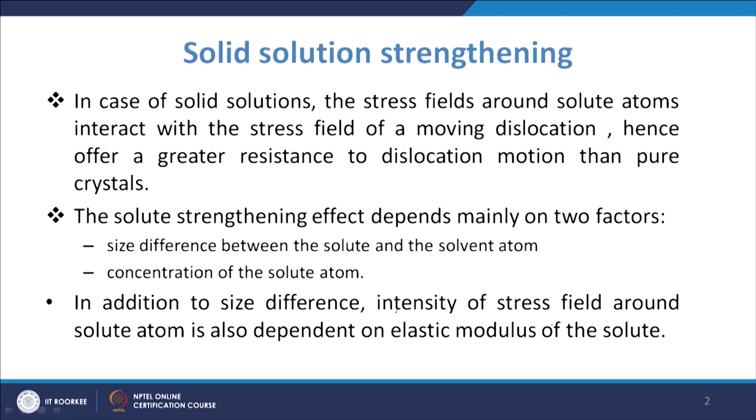As we discussed, in solid solutions the stress field around the solute atoms interacts with the stress field of a moving dislocation. These two stress fields interact with each other, and in that process a greater resistance is offered to dislocation movement in solid solutions than in pure metals.